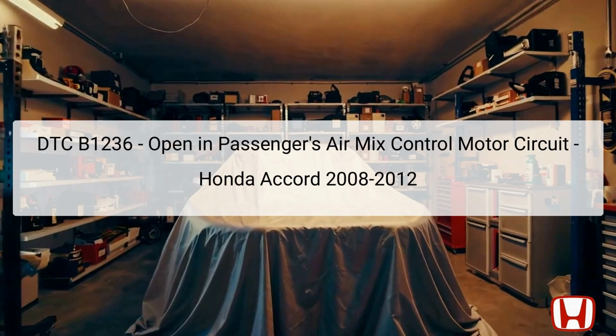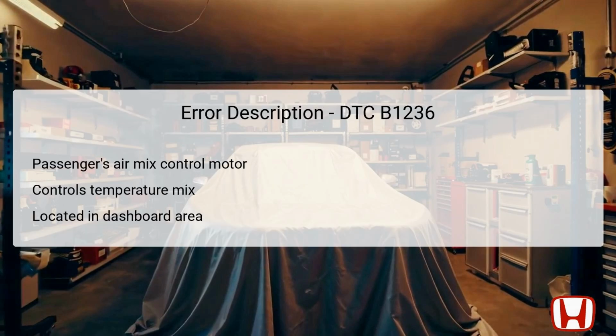The error description for DTC B1236 specifically points to a fault in the passenger's air mix control motor circuit. This motor is responsible for regulating the mix of heated and cooled air coming into the cabin, thus enabling the climate control system to maintain desired temperature settings. Its precise location is typically within the dashboard assembly, close to the climate control unit. By adjusting airflow, it plays a critical role in ensuring passenger comfort during varying driving conditions.